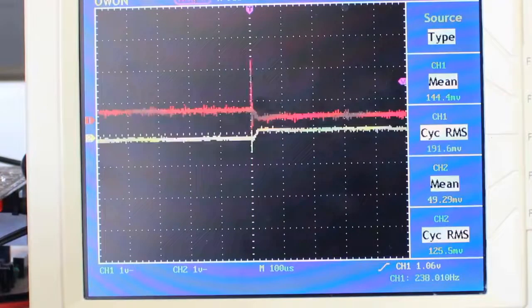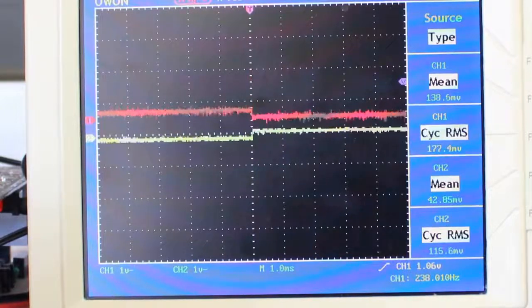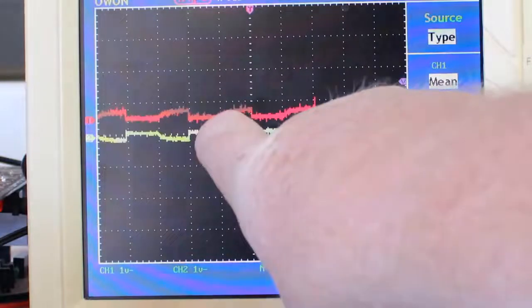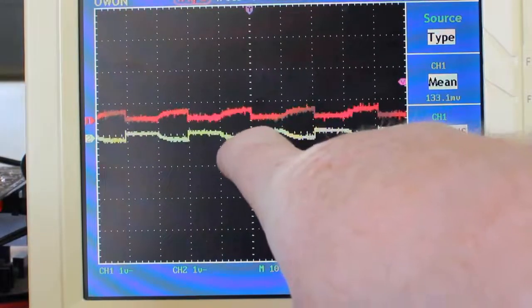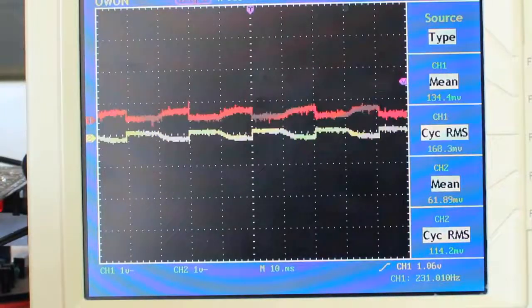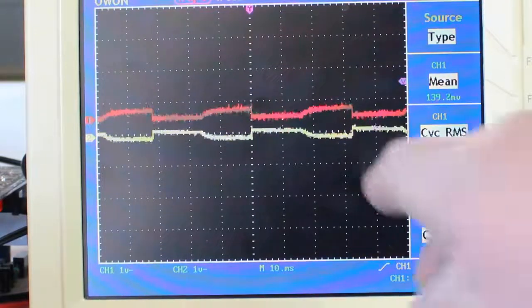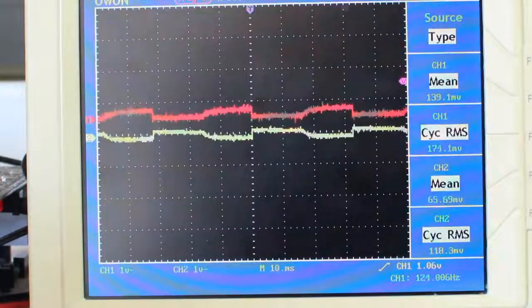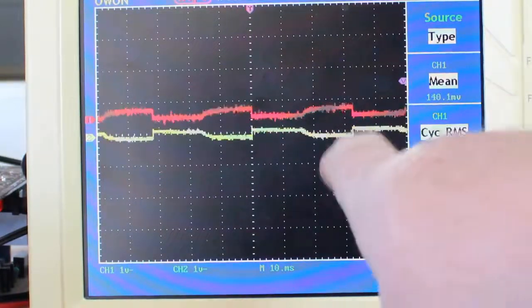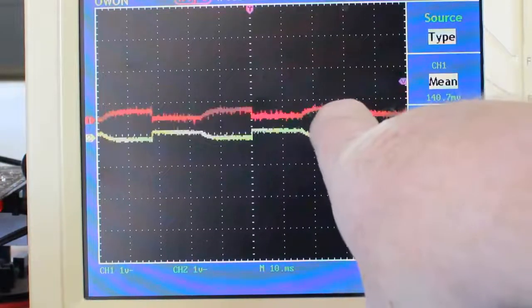And again, we can see, if we go back, where's our zero? Yeah. Go back here. These curves here are the change. So that's the change. When we flat top, if there's a flat top at the top, there is no change. So the flat top itself, for example, if we were to put that right out, we slow down the frequency at the moment with 31 Hertz, and you can see there's quite a flat bit just in here, both top and bottom. So the flat bit there is no change in current. So there is no magnetic force, and therefore it cannot create a voltage. The voltage is being created over here where it's curved and where it's changed. Once we get up to a certain point, then there is no more voltage created.